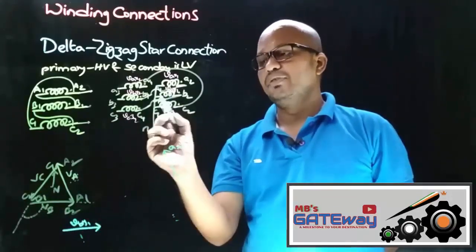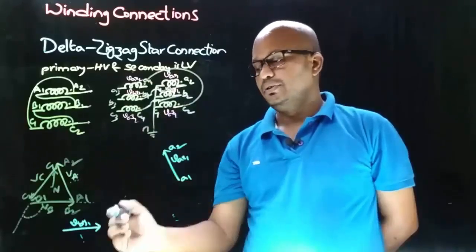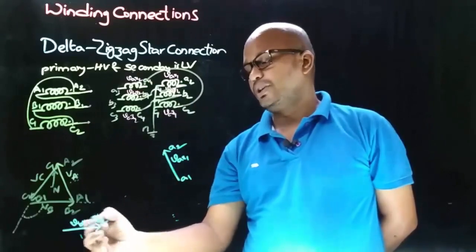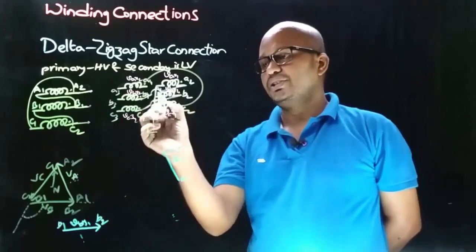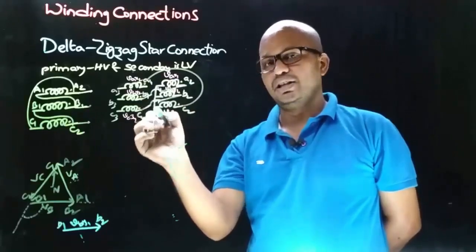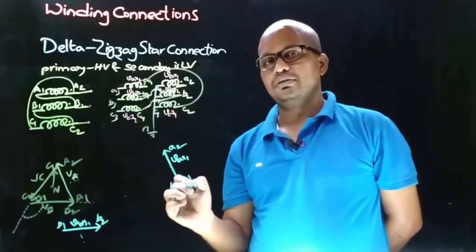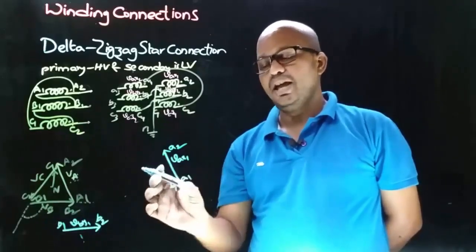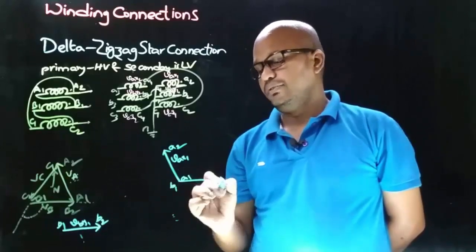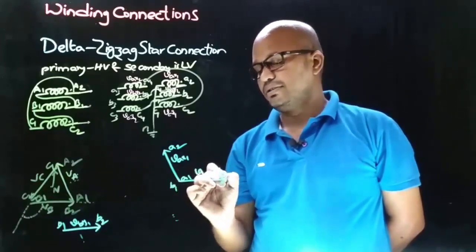The terminals are B1 and B2 and the connection is taken from dot end, that is B2. Therefore the arrow will point towards B2 and the other end will be B1. Observing the winding connection, to A1 there is B1 connection. So in the phasor diagram, to A1 there must be B1. Therefore draw this VB-Y1 phasor such that A1 will have B1. Therefore the VB-Y1 phasor is like this.